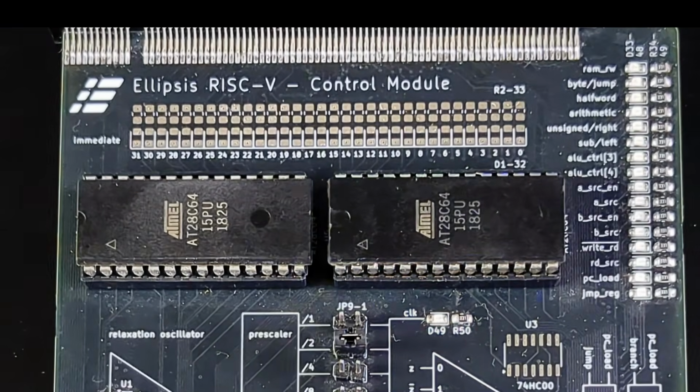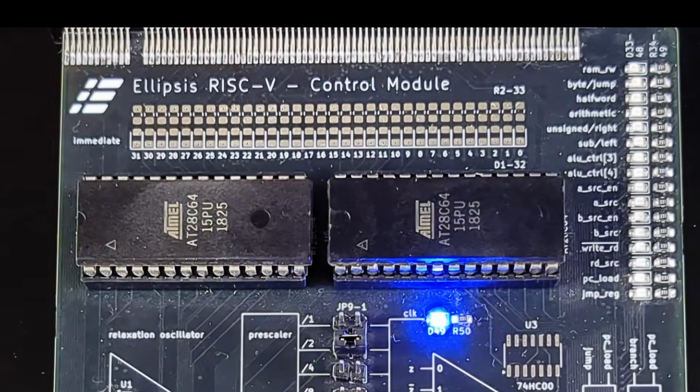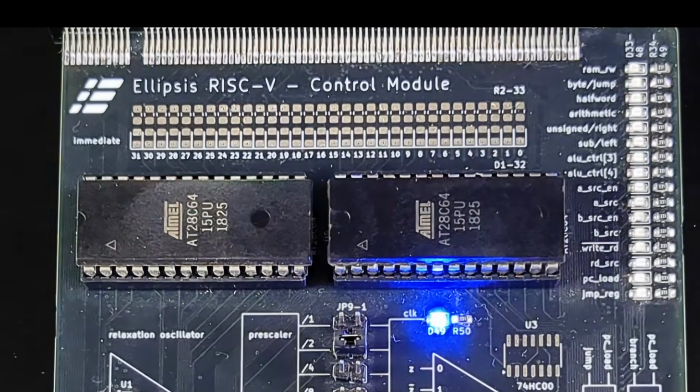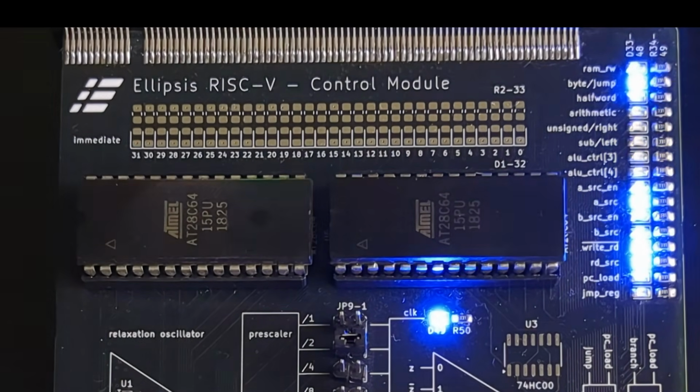I have a program running on the test board that reads in the clock, and every time it gets a rising edge, it steps through the 9 addresses of the test program that's loaded on the instruction ROMs. But again, that doesn't look right. Control signals that should be showing are not. So again, I'll need to do some debugging. Well, at least this time I know exactly what the problem was.